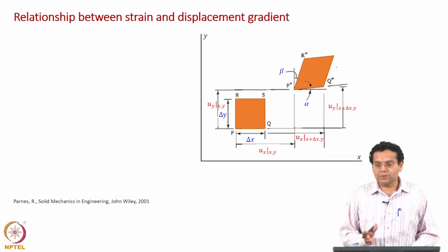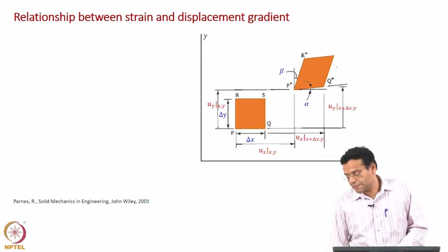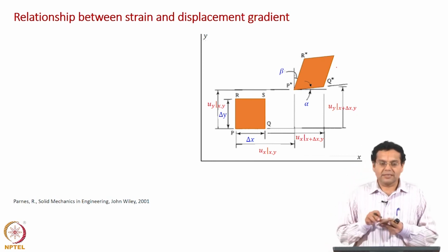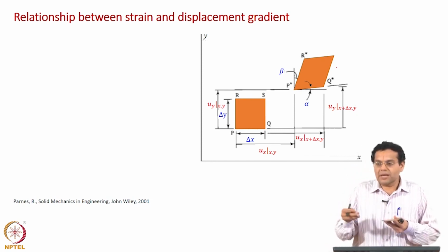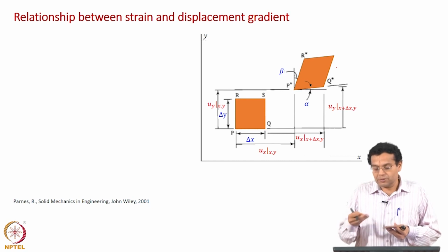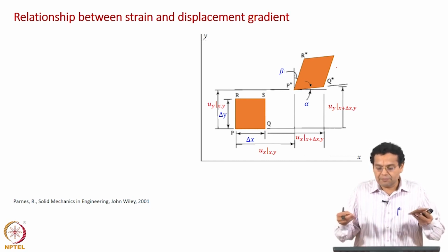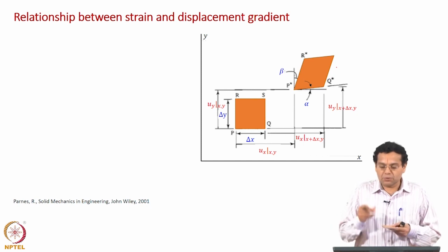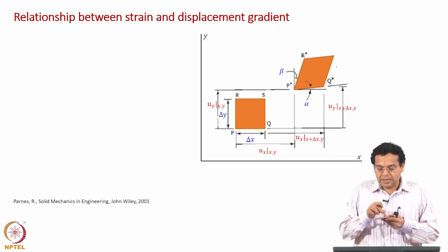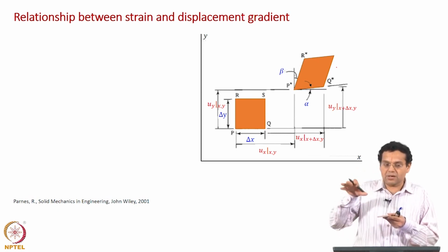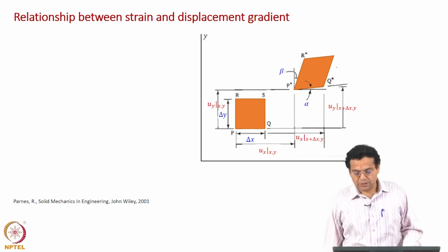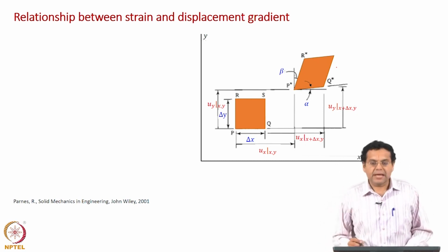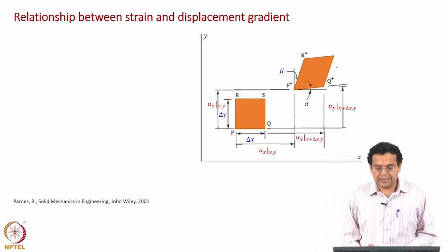One is, as I told you, a plate, which is easy to understand. The other way you should understand is that it is a square region inside a solid object, because as we go along, we will shrink the plate to a point as usual. Then of course, you can't say it is a plate. So, two ways of imagining: a plate to usual observation, or a two dimensional region in a solid object, and that is denoted by PQRS. The lengths of the sides are delta x, delta y.